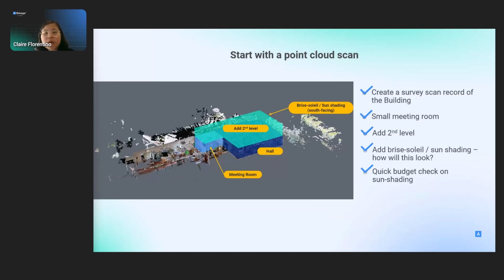One thing that you may have noticed is that we did everything today in BricsCAD, but in case you wish to further enhance, let's say, the render, or you needed some fantastic lighting effects, or maybe there are certain third-party tools that you're just comfortable using, BricsCAD has direct links with Twinmotion, with Lumion, and if you are comfortable with Enscape, BricsCAD can export an FBX file that you can bring into Enscape and basically do what you need to do there.